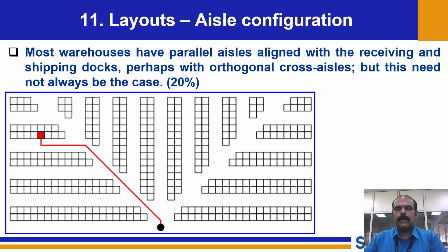And next is another configuration: parallel aisle or perpendicular aisle, or in some cases mixed aisle. What the research says is we can save 20% of the distance like this. It is a combination of parallel as well as perpendicular aspects. Here it is perpendicular, but here it is parallel, so now it is very easy for us to maneuver in between. Likewise, all sorts of creativity can be penned in here, and using an assignment problem, layouts can be optimized to a greater extent.